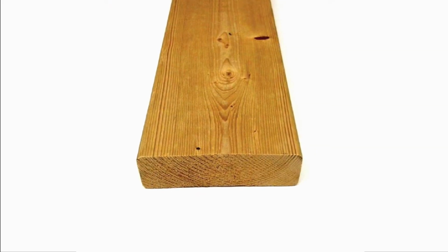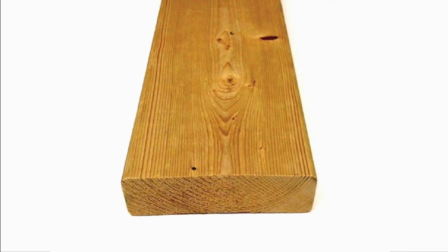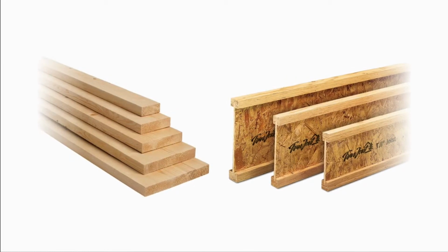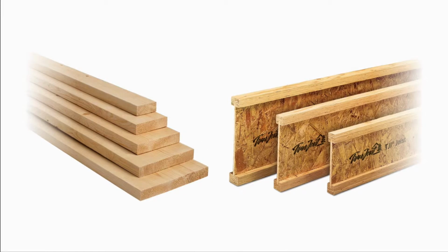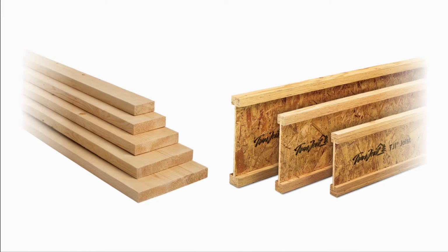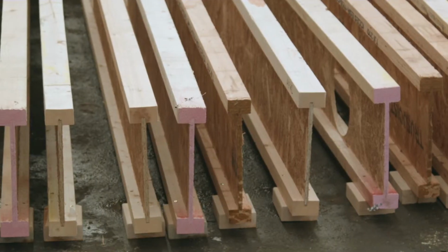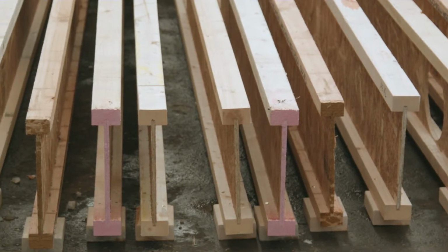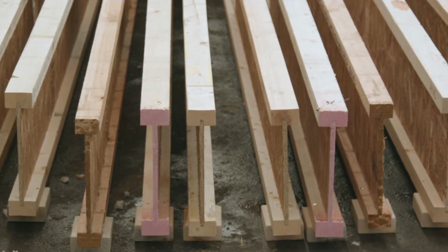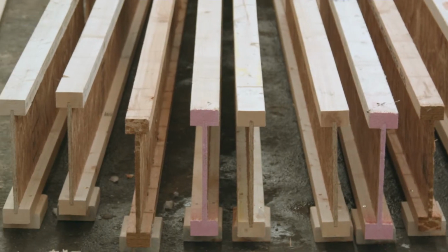Engineered wood I joists are quickly replacing dimensional lumber joists and are becoming the industry standard as they are more effective and efficient. This introduces many more possibilities in building design for engineers. They come in varying sizes for depth and lengths, minimize deflection, and can be modified to hide utilities that would otherwise require a bulkhead or drop ceiling to be concealed.